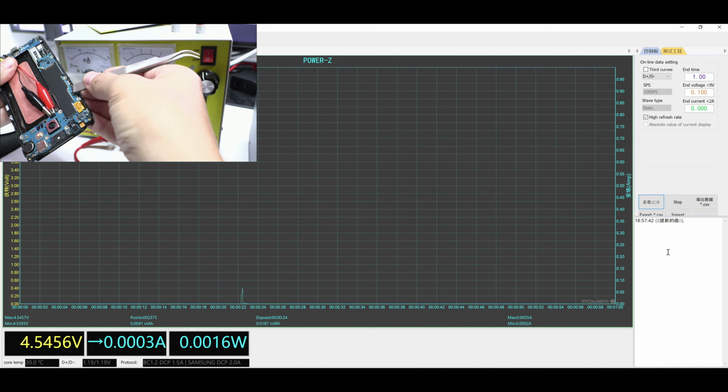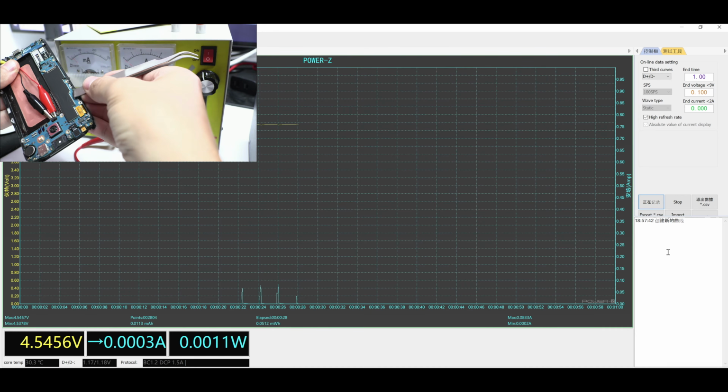Depending on the range of the device, the current can reach 200-250 milliamperes before the image appears. This is when the PMIC, CPU and memories start to act.